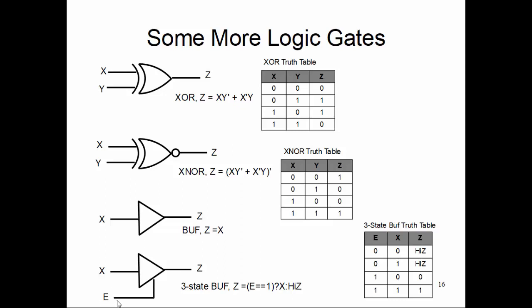There are applications of such gates, especially in memory, bidirectional data path design, and we'll actually be seeing this specific application of the tri-state buffer conceptually during project 2, and physically when we implement things at the gate level, we'll see it in project 3. Okay, we need to use the tri-state buffer there to make an in-out kind of port out of this memory, or any other digital component which actually supports in-out type of IO direction. We need to use a tri-state buffer like this one.